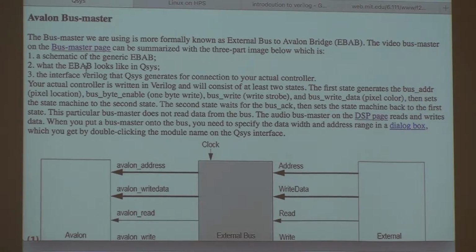You have to be able to read the FIFO state, read the voltage level of the left and right channel, read the FIFO state for the right, and then write the left and right channel. And the way the FIFOs work, the left and right channels are always in sync. You can't play a new voltage until there's a FIFO entry in both channels, so I'm not sure why they have a FIFO counter for each channel separately. But they do.